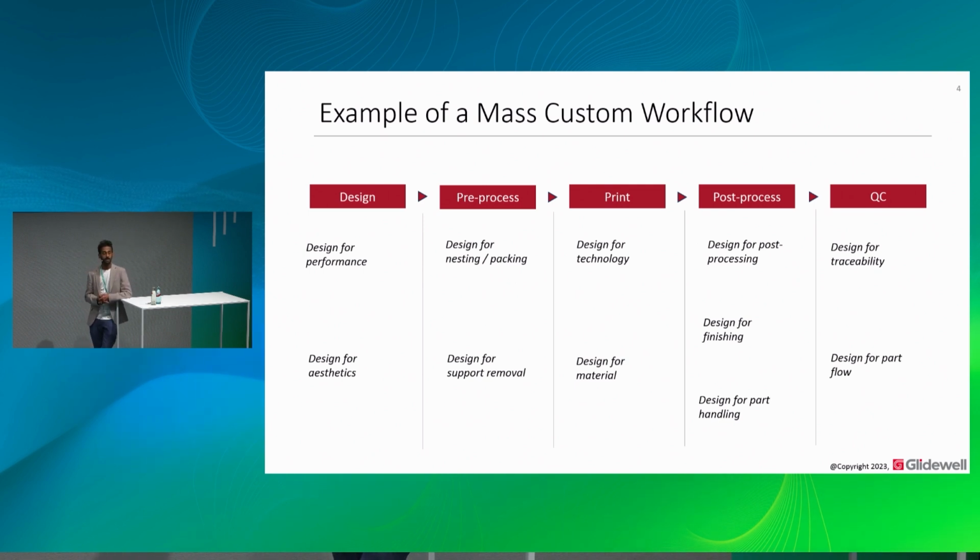So we make a few thousand of those every week, and for a photopolymer process, the post-processing really is unloading things off a machine, the IPA washes, the curing step, and all of that. The finishing, however, is different, because we're sending these to dentists, and every single part we make is unique, right? Essentially, these are batches of one. If we make a few thousand of these every week, we don't ever print the same guard twice. Unless we did something wrong, that's just not something that happens.